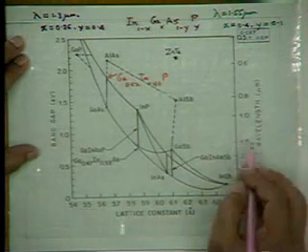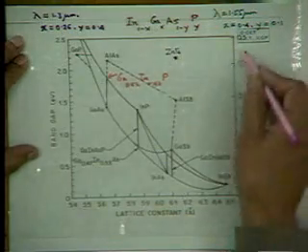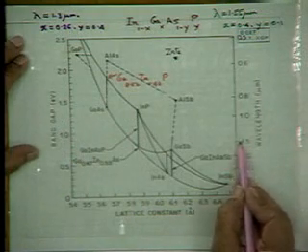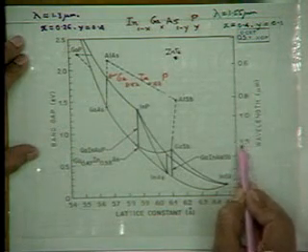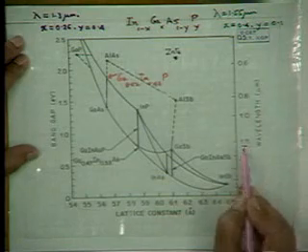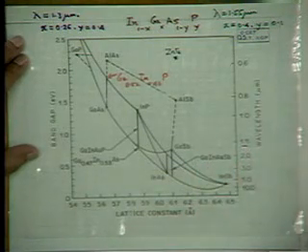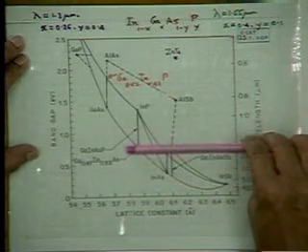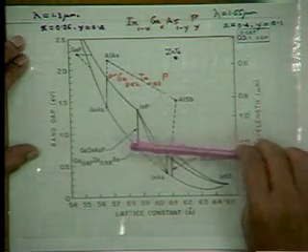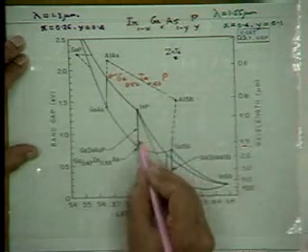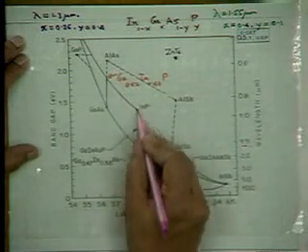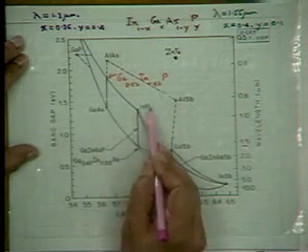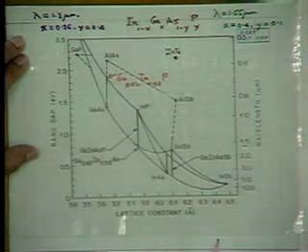If we are looking for one, on this axis we have the wavelength corresponding to this band gap. So if you are looking for emission at a wavelength of 1.5, and if we draw a horizontal line, we find that this intersects this vertical line for a given lattice parameter corresponding to a lattice parameter of indium phosphide.